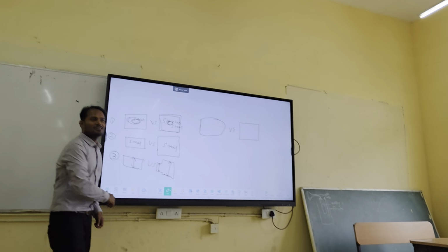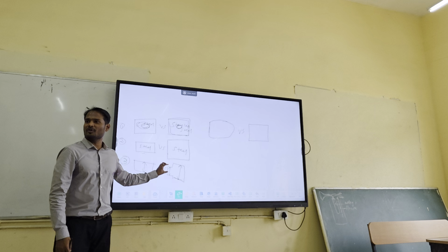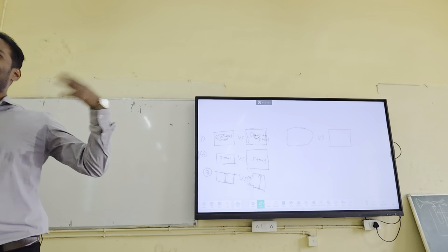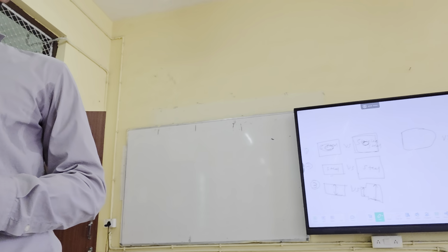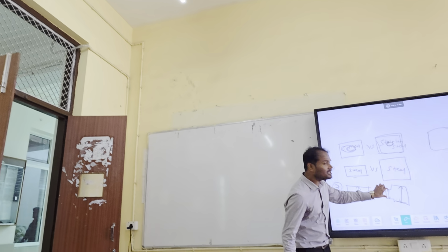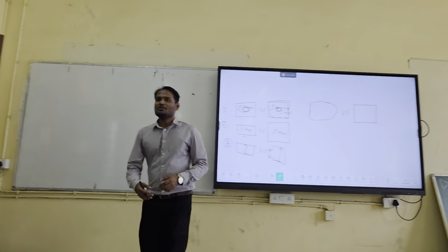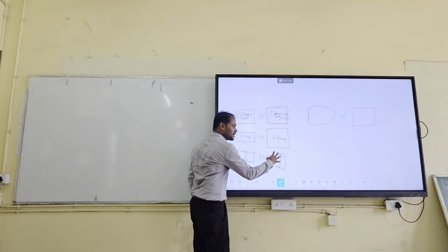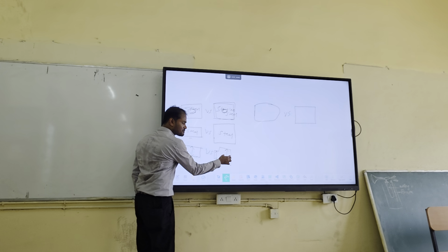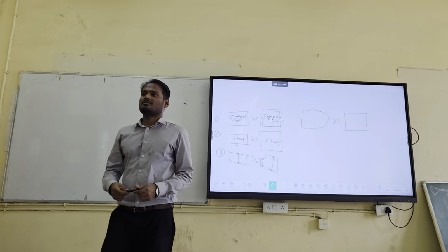Now this one and this one. This is a uniform shape, but this shape is not uniform. Somewhere it is less thick, somewhere more thick. So, of course, the right side needs slow heating, because for this portion heating will be fine, but for this portion it will take time. If you provide a high heating rate, then between this part and this part there will be a temperature gradient and it may crack.